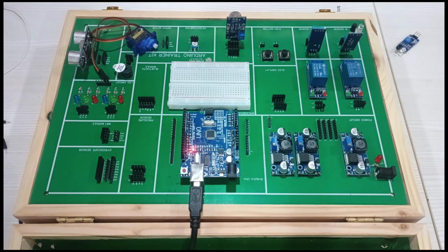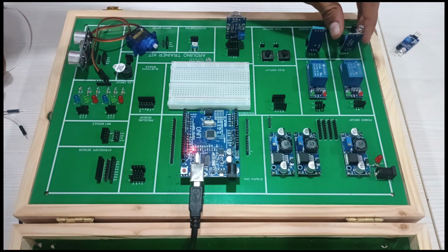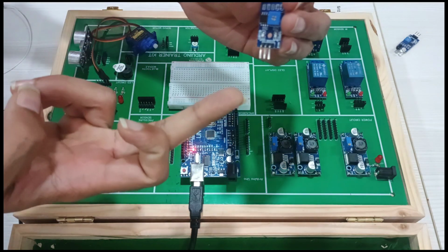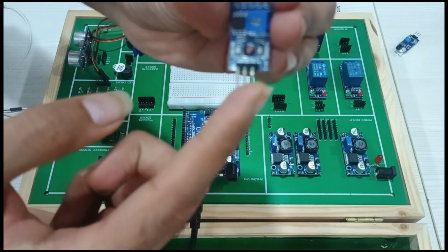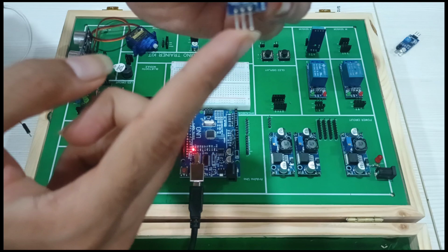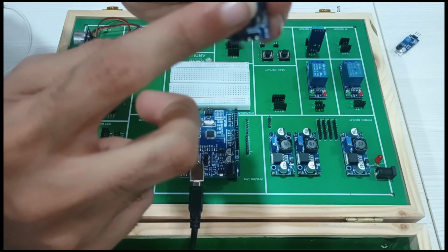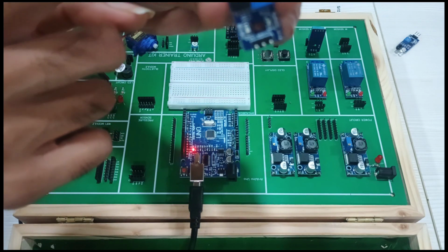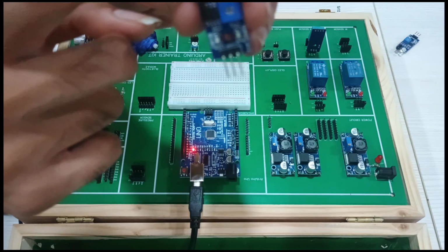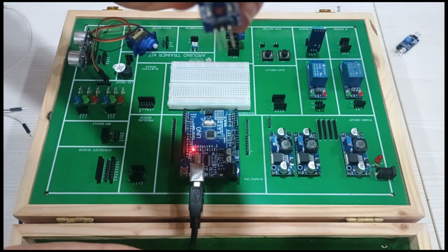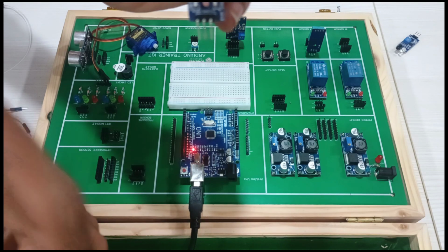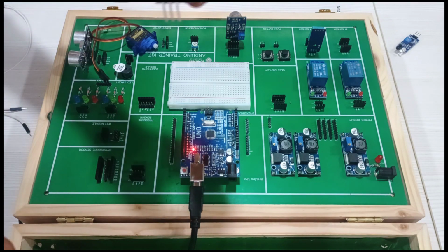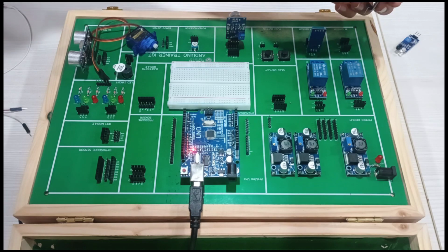Now the IR sensor module. So let's start the connection. As you can see, this is the IR sensor, in which you can see 3 pins: output, ground, VCC. This works on 3.3 volts, and you can see a potentiometer to change the sensitivity, and we can see an IR transmitter and the IR receiver. It sends the data in infrared light and takes the output by using the receiver. So let's start the connection.